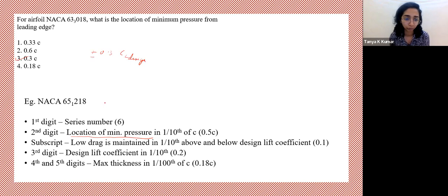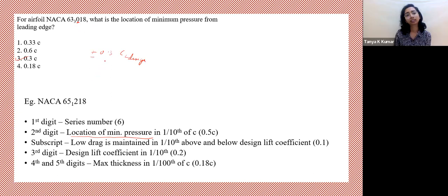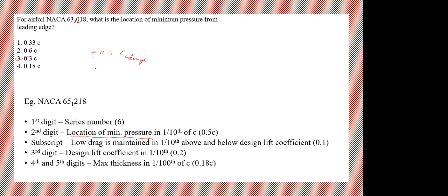Then what is the design lift coefficient? In this, it's just 0. Can a 0 lift coefficient be there? For a symmetrical aerofoil, CL not is 0.